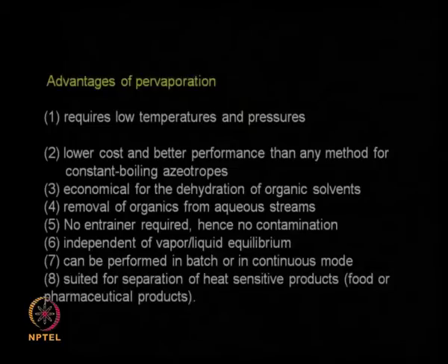Actually many advantages are there. It requires low temperature and pressure because you are using a vacuum and you just need to put in some heat so that the liquid is vaporized. So obviously the temperature of operation is very low. So it can be used for temperature sensitive material, the energy usage is less. So these are the advantages.